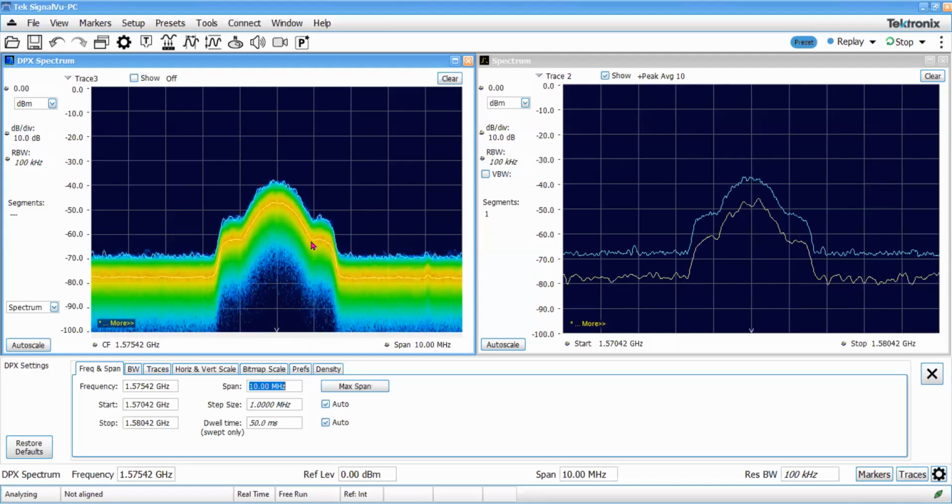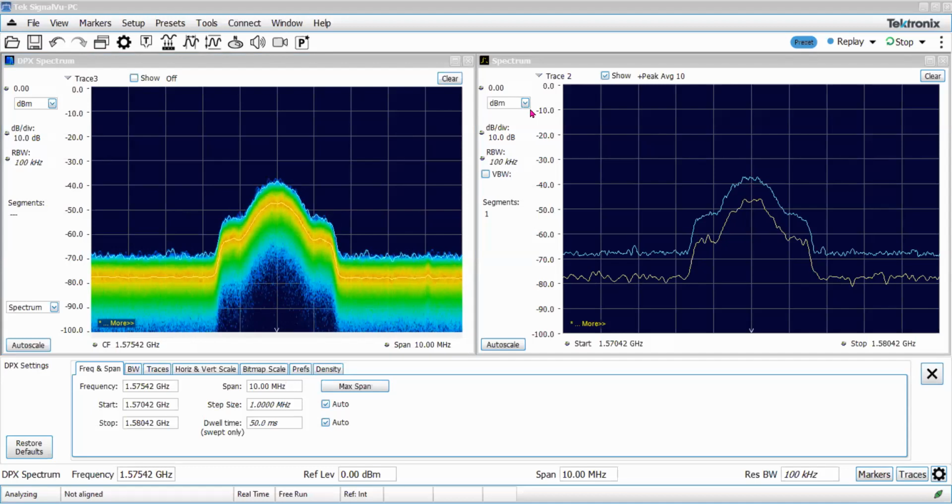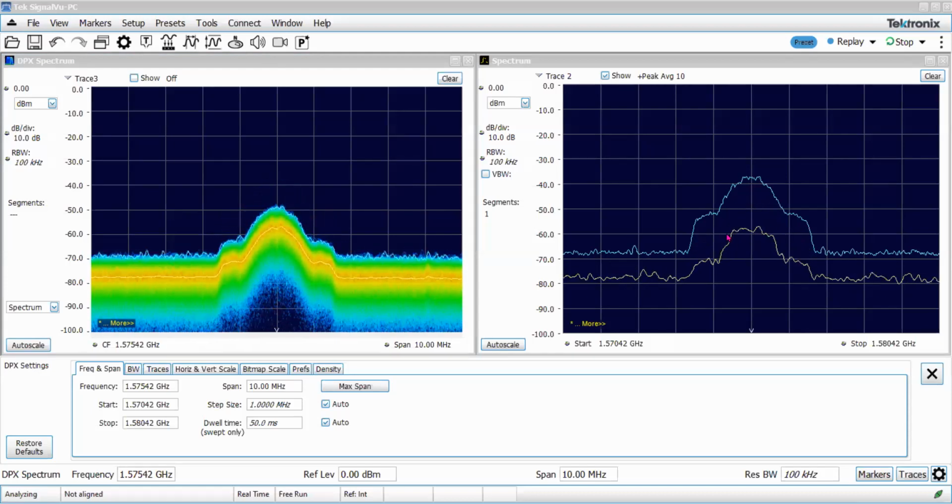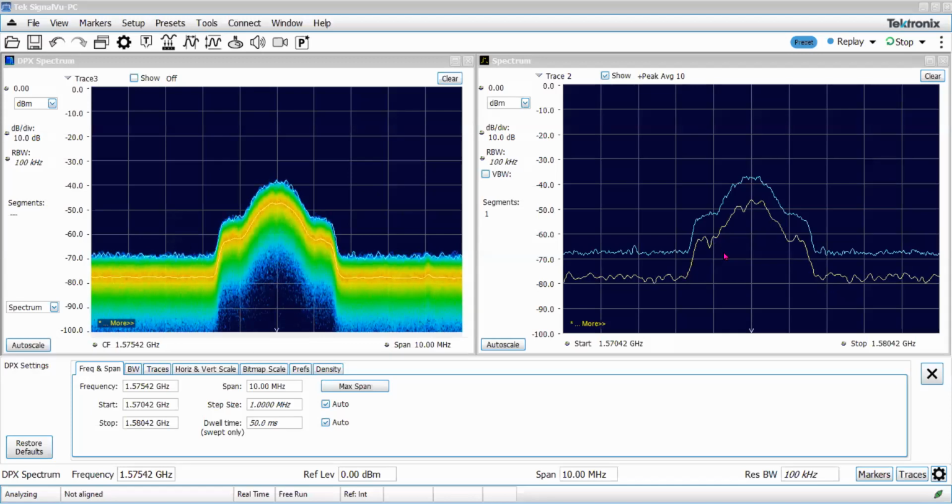Now, I can change many things here. I'm continuously sending the signal. We can change the power here. I have put maybe 20 dB. If I increase the attenuation by 10 dB, this power should go down by 10 dB. Okay, you see now this decreased by 10 dB. Or we can increase it. I can change to 10. So it increases. We can change many things here.